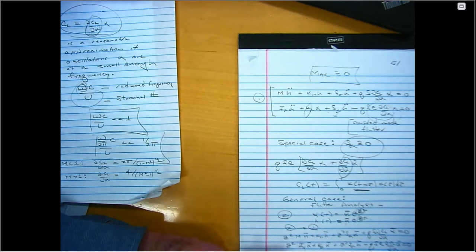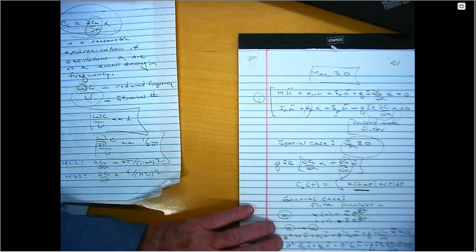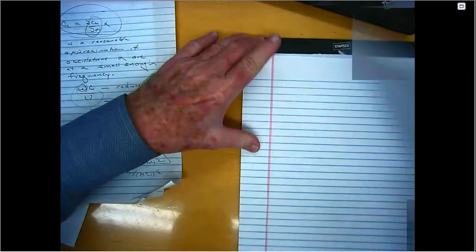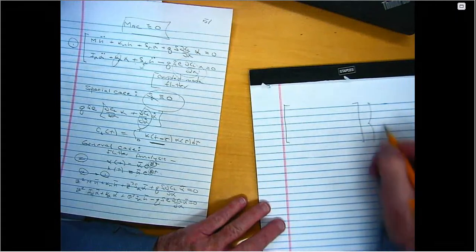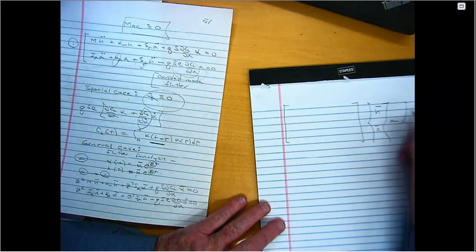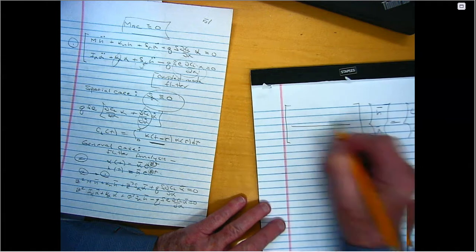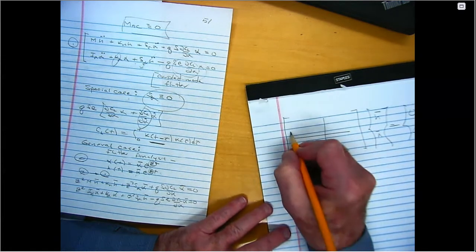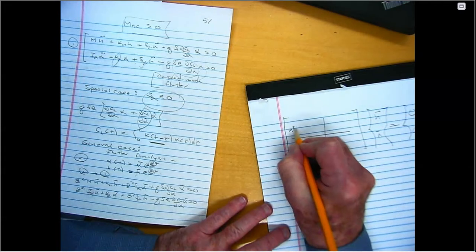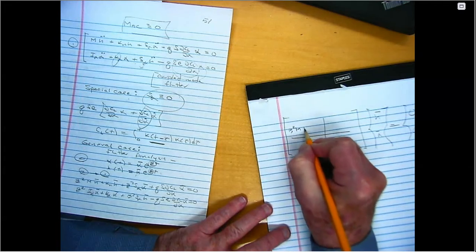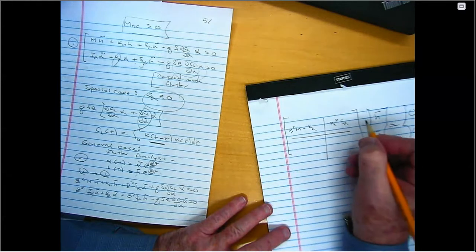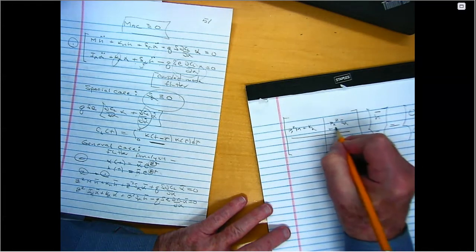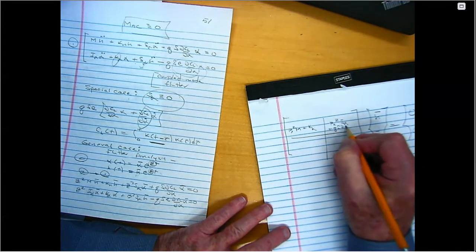But I can also write that in matrix notation, which every good flutter engineer must do. So in matrix notation, it's a 2x2 matrix, because it's a matrix equation. I have H bar up here, I have alpha bar here. On the right-hand side now I have zeros. And over here I have beta squared m plus k sub h, beta squared s alpha, plus q s dCL d alpha.